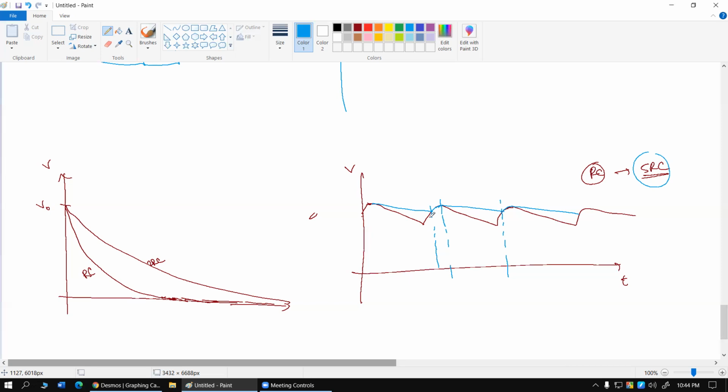But if you take the same thing from the outputs of a cell phone charger, for a regular scale, it would appear perfectly straight. But if you start to zoom in onto the graph, eventually there would come a point when you will be able to see these small fluctuations. You have to understand that whenever we convert AC into DC, these fluctuations are unavoidable. But by designing the circuit well, we can reduce the amount of these fluctuations. Crazy, but good.